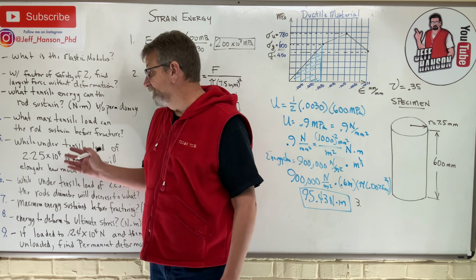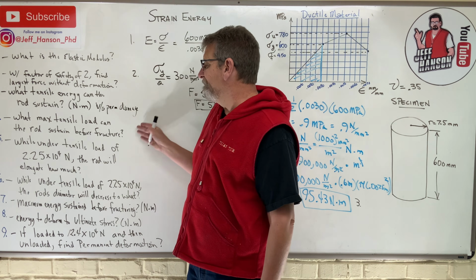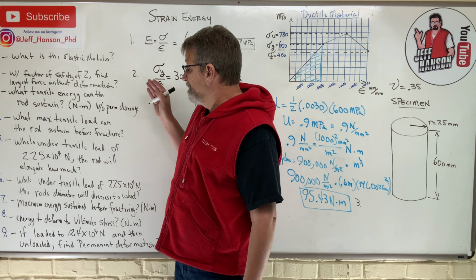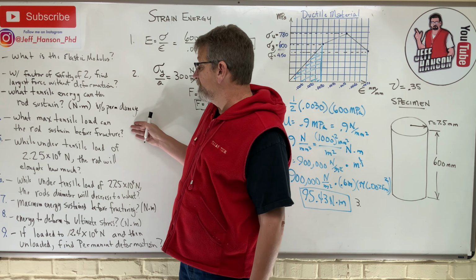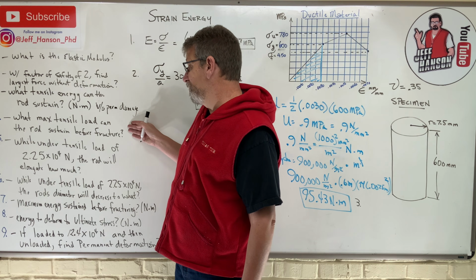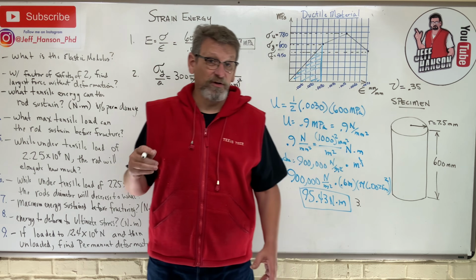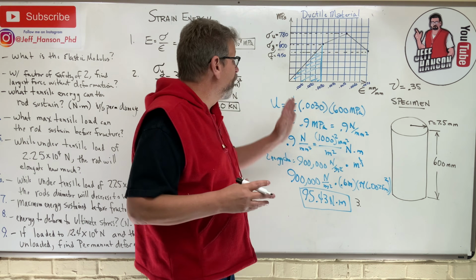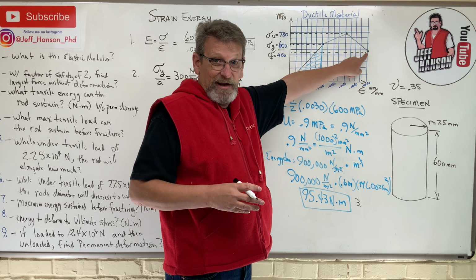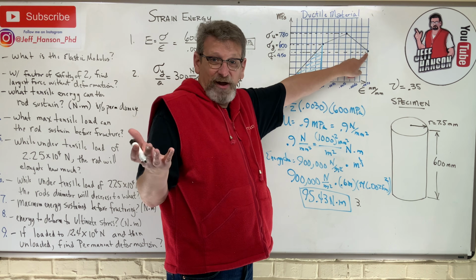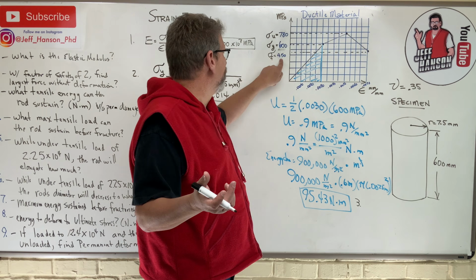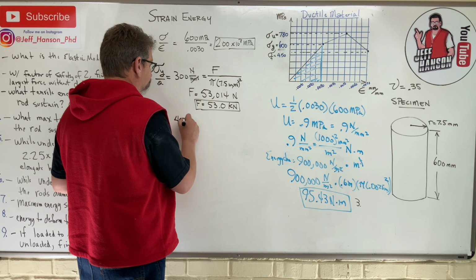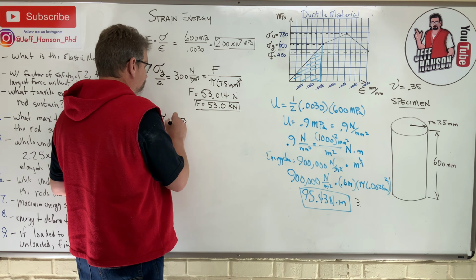Number 4, what max tensile load can the rod sustain before fracture? So we're trying to find a force on the rod. What's the biggest force we can apply to the rod before, bam, fracture happens, okay? Where does fracture happen? At 450, right? So 450 is sigma fracture.